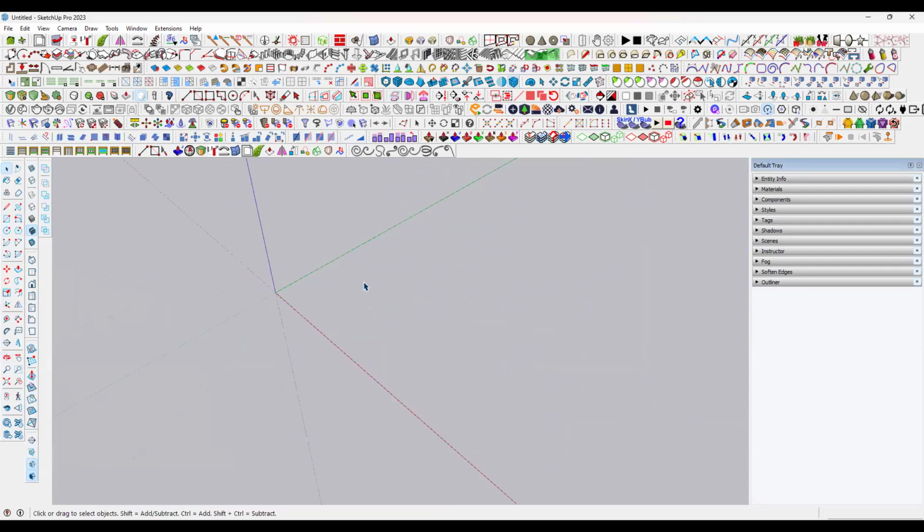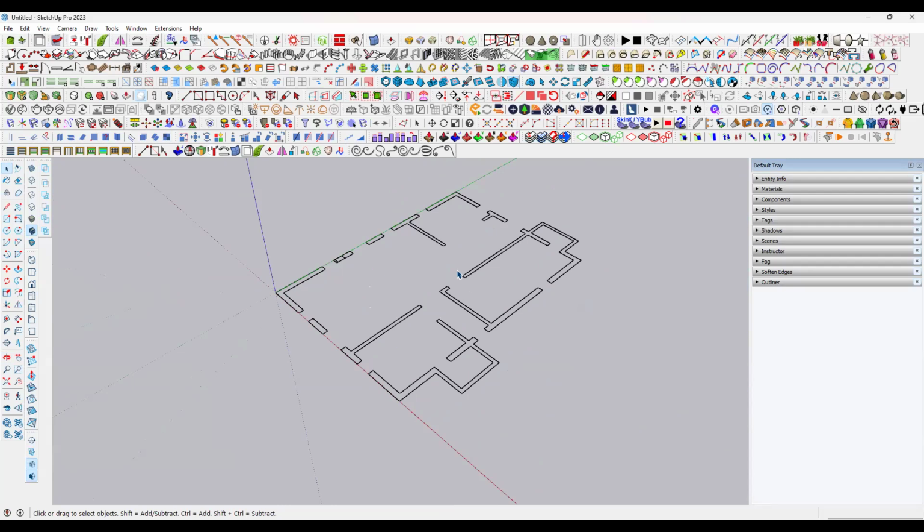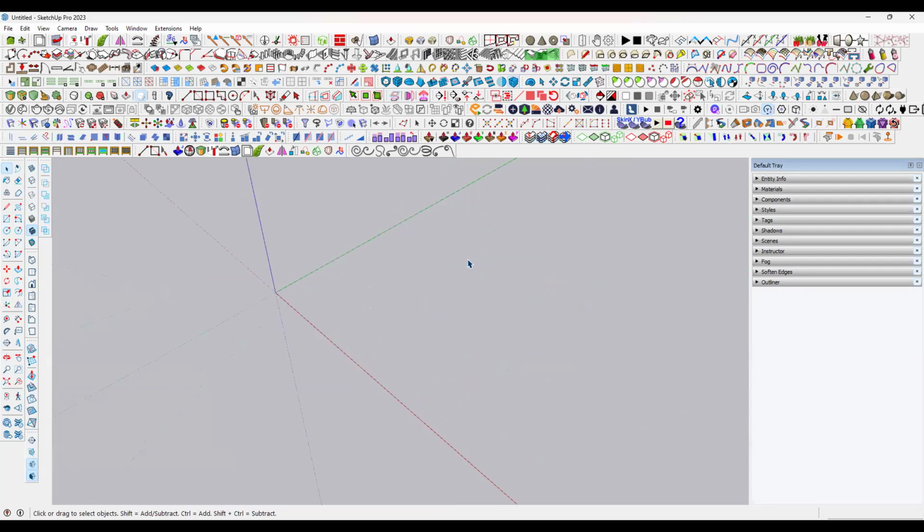But along with the AutoCAD file, if you have dimensions or text and so on, we don't want all that, because if you import unwanted text into SketchUp, the 3D model size is going to increase. If the 3D model size increases, automatically the system also gets heavy. In that situation, instead of taking unnecessary data from AutoCAD, we have to take exactly the files that we want.